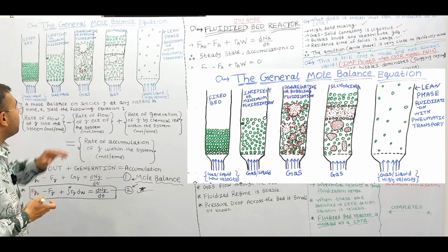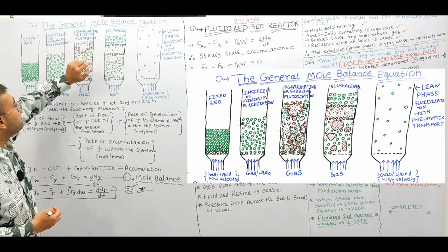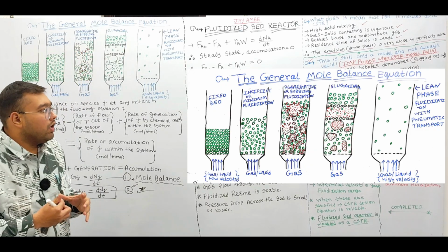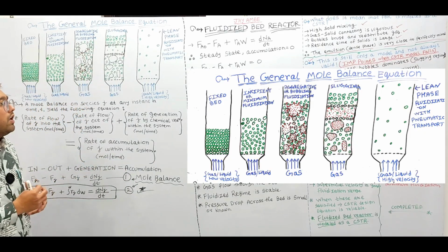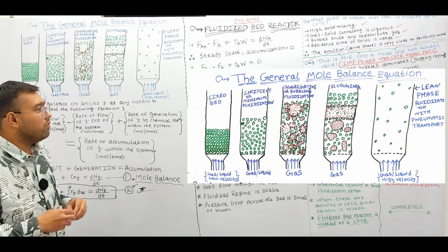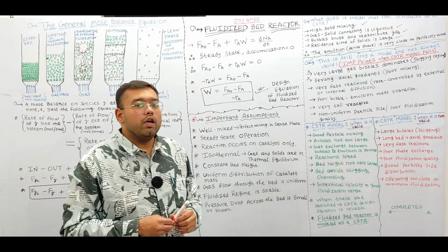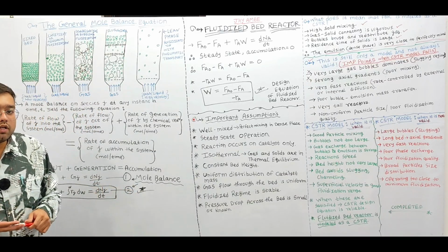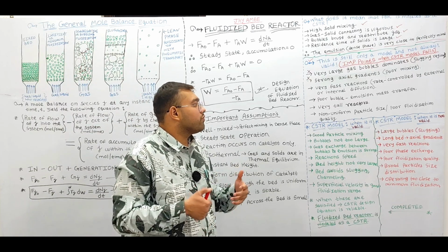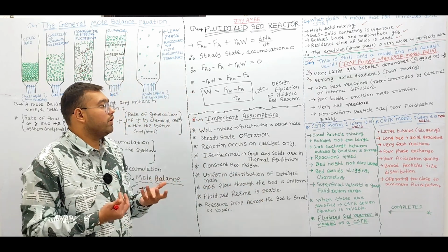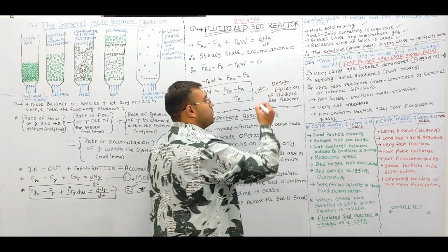The gas which is present in the bubbles will diffuse or leak into the emulsion phase, on the solid catalyst. So the internal diffusion and the external diffusion of the gaseous phase on the solid catalyst surface will result in a very fast reaction or variation in the rates of the reactions. Due to the limitations of the internal diffusion or the external diffusion, this results in very fast reactions or no reactions, right? So during those conditions, the CSTR model fails, right?